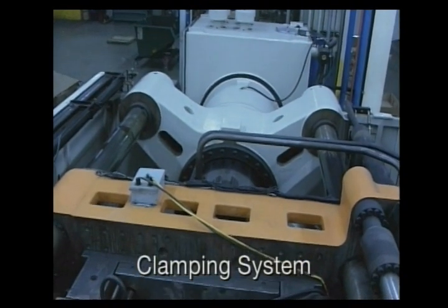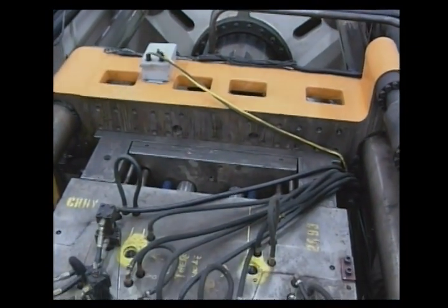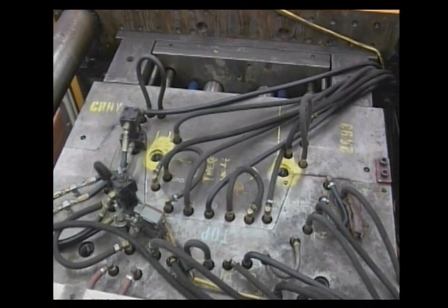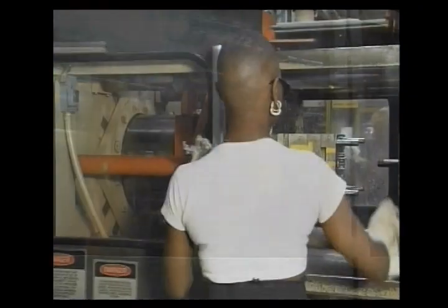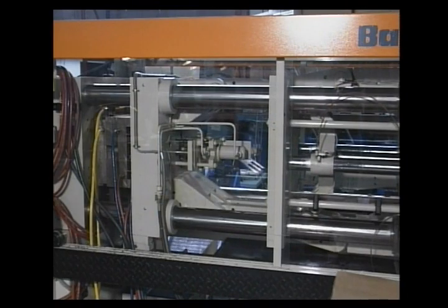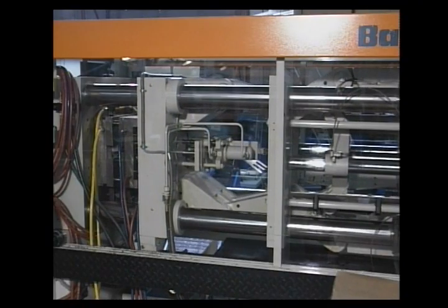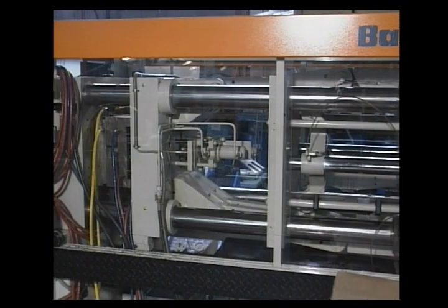The function of an injection molding machine's clamping system is to keep the plastic material from leaking out or flashing at the parting line of the mold's cavity and core. The clamping system has 2 configurations. One is a fully hydraulic system where the total clamping force is generated by the hydraulic clamping cylinder. The second is a toggle system where a much smaller hydraulic cylinder is used in conjunction with a series of toggle levers to provide the full clamping force.